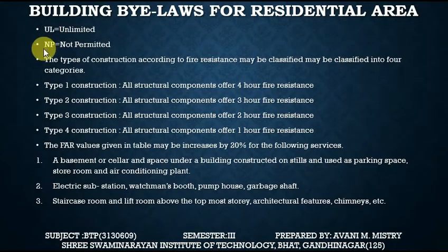UL means unlimited, NP means not permitted. The type of the construction according to the fire resistance may be classified into four categories. Type 1 construction, all structural components offer 4-hour fire resistance. Then type 2 construction, all the structural components offer 3-hour fire resistance. Type 3 construction, all structural components offer 2-hour fire resistance. Type 4 construction, all structural components offer 1-hour fire resistance.